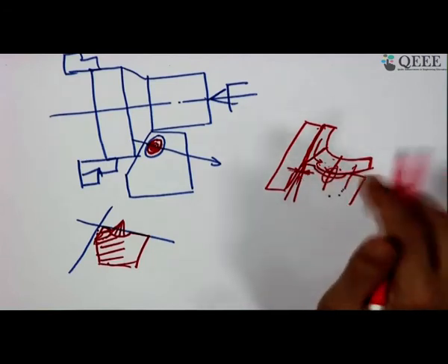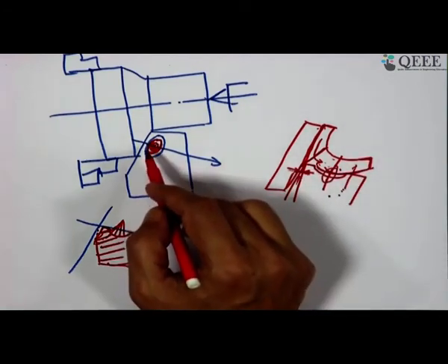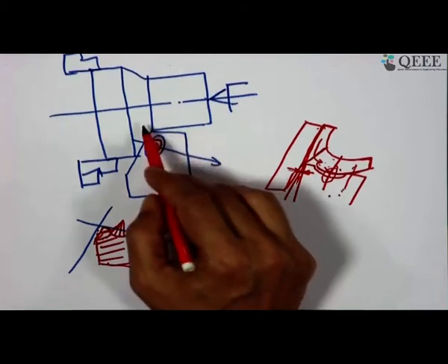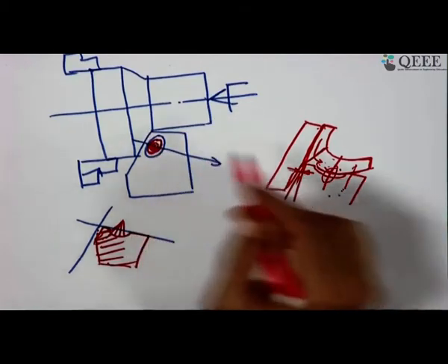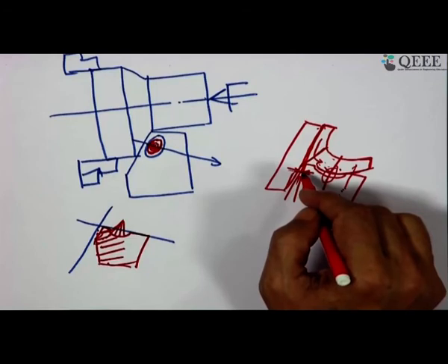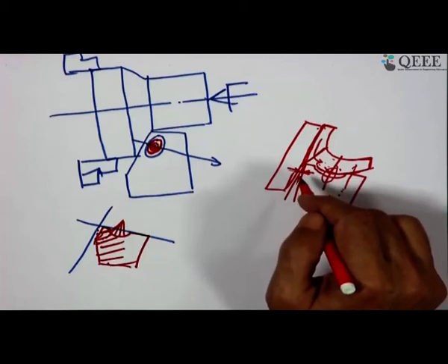But it has been found that if we go to very high speed machining with this ductile material with this tool, then also temperature can go to that threshold point where the wear phenomenon is no more mechanically dominated, but it is also chemical in nature.